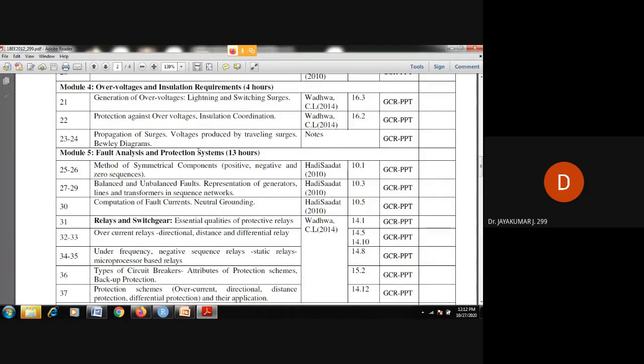The last one is contingency analysis. Contingency analysis means during an emergency, such as an unexpected flood, huge thunder, or heavy rain, when the transformer and other equipment have collapsed, how my system is performing. That is called contingency analysis. So these are the 5 analyses a power system engineer must know.